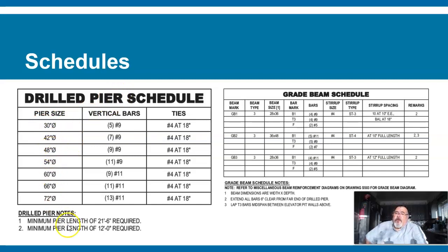And these piers vary in different sizes. You would refer to this schedule so you'd know to drill the right size hole for that pier. And over here is the grade beam schedule. So again, lineal footage of a type of foundation.